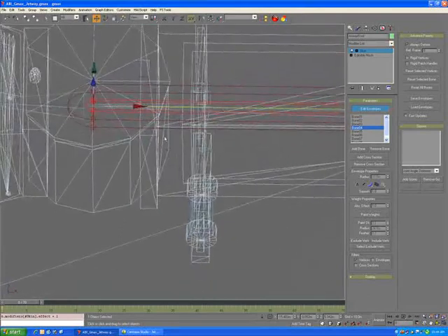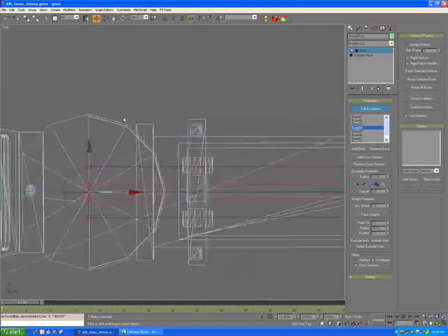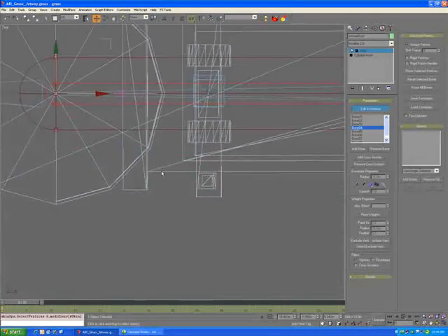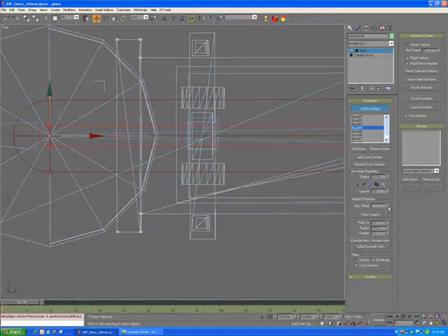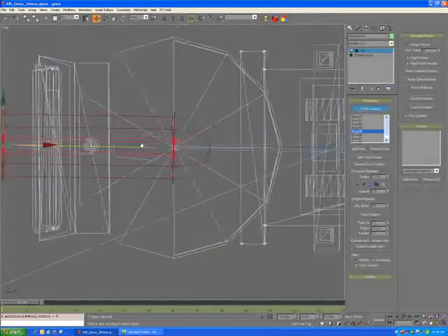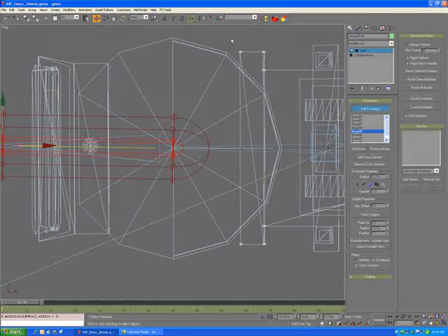In this case, you may want to change views, like to a top-down view, so you can get a better grasp on these particular vertices. Turn all these up to 1. Now bone 5 is going to be the rounded portion here at the end. To make this a little easier, I'm just going to select all of this for now and assign it all to bone 5.